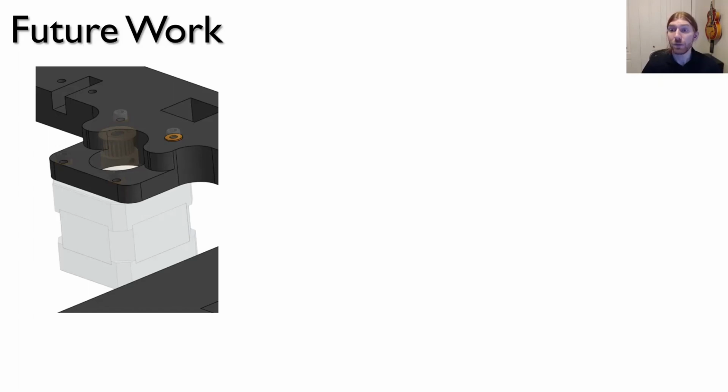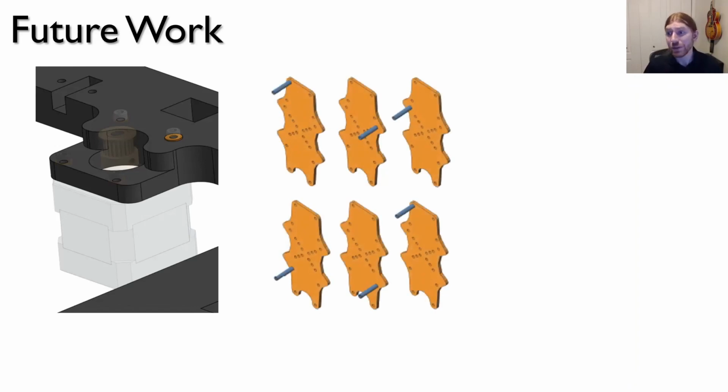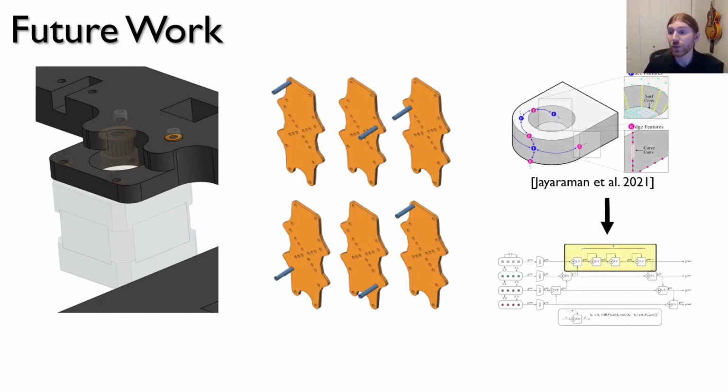We would like to incorporate more parts into an assembly context when predicting mates to better capture design intent. Complementary to adding assembly context, we'd like to further explore interaction techniques to capture design intent in ambiguous situations. Finally, we would like to incorporate more intrinsic geometric features. Concurrently developed BREP graph networks do a good job of this, and generally follow the same convolutional patterns as the metapath portion of SBGCN, and so are good candidates to incorporate within the SBGCN architecture.